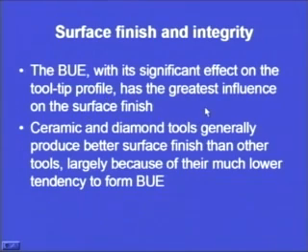surface finish. In the previous lecture we have seen certain conditions for how we can reduce the formation of the built up edge. It was seen that sometimes it is advantageous also, but the limitations that come with the advantages have to be removed. If the built up edge has a significant effect on the tool tip profile, then it is directly going to influence the surface finish of the final product that we are going to produce. So, the surface finish that we get may not be according to our desired levels.